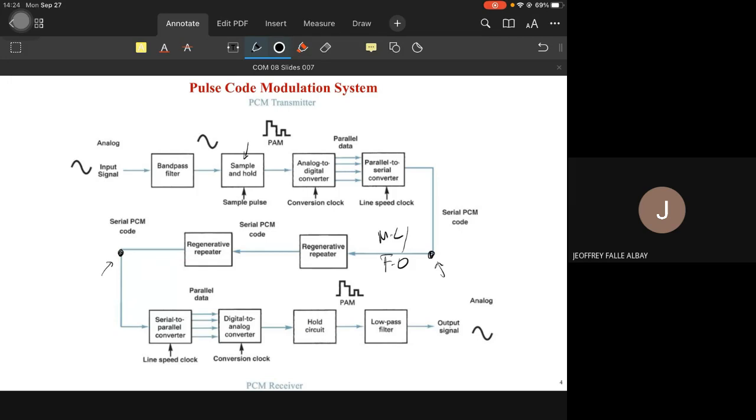Our signal may degrade in voltage level, say from 2, 3, 4 volts for ones and zeros, but the ones and zeros are still distinguishable so they are not totally lost. We just regenerate or recreate them, so noise does not get in. We know that an amplifier would amplify the noise, so in this case there is none.